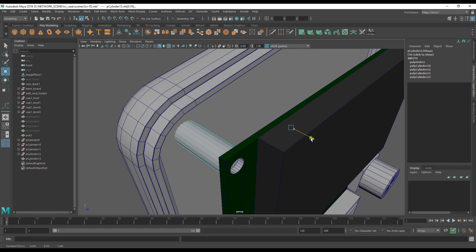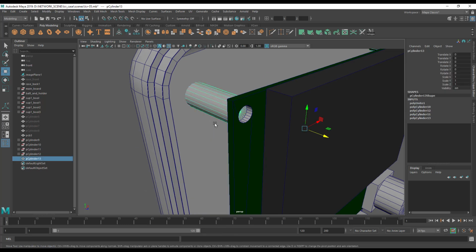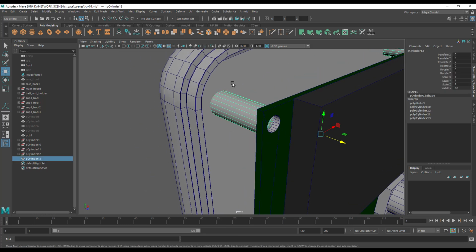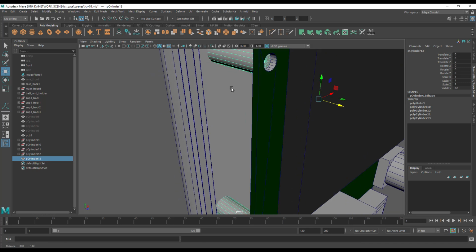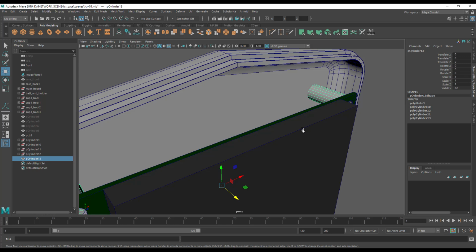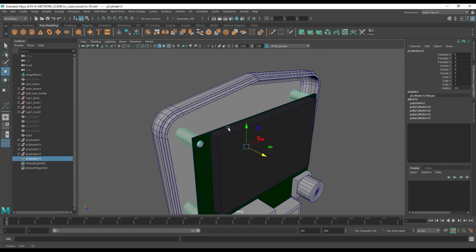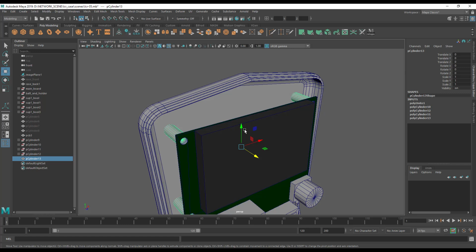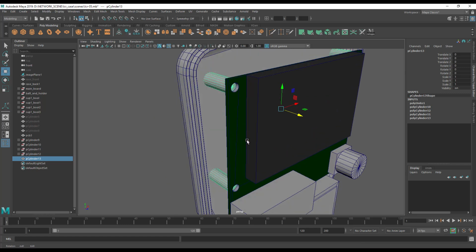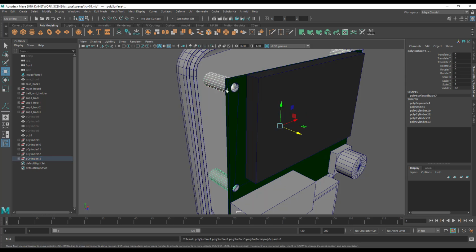So as I've probably mentioned with the battery holder, if you have an object in Maya that is intersected with another object, when you come to 3D print this, it will actually see it as all one object. So we don't need to bother with a union boolean or anything. This will be absolutely fine for 3D printing. Now we need to make holes in these, so I'm going to separate them again. Mesh separate. There we go.